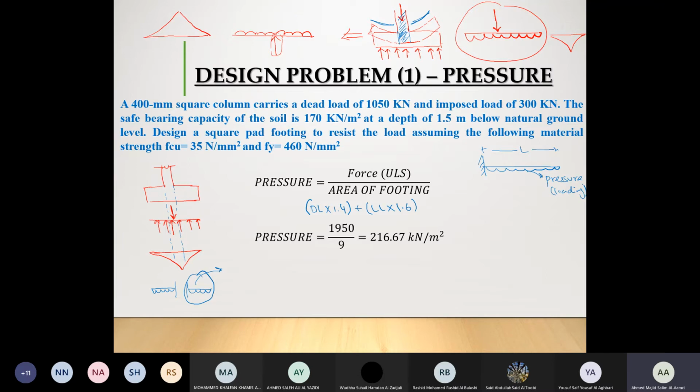Since there is a weight of the foundation itself, you will see that it will contribute to the ground pressure. But when we talk about bending moment, this particular element, which is the foundation, is already settling, kept in a soil. It will not bend. It will start bending whenever we start to load the column itself. So when we are calculating the bending moment, we should take the ultimate limit state, because we said we are always designing our reinforcement for the critical scenario. The second thing, we don't include the self-weight.